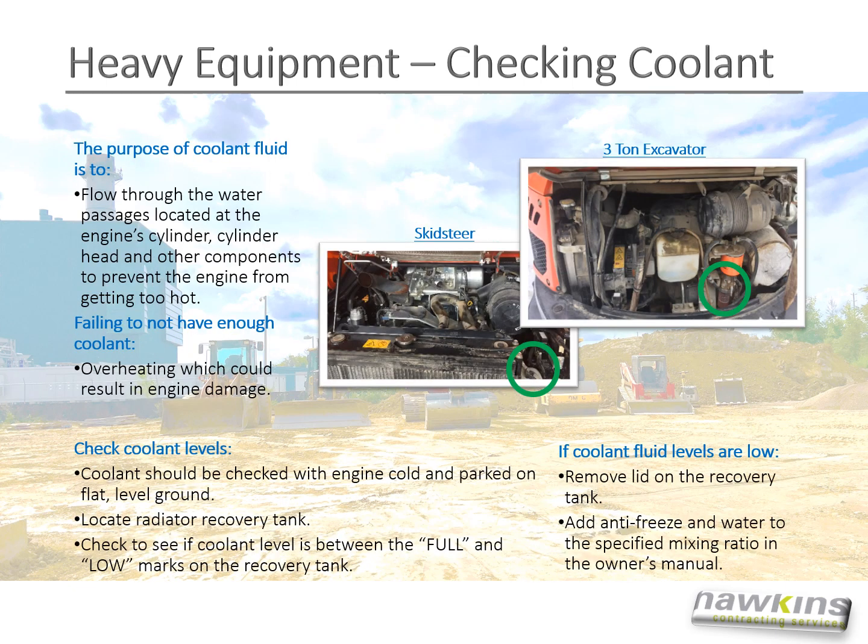Checking coolant fluid. Coolant should be checked with engine cold and parked on flat, level ground. Locate the radiator recovery tank. Check to see if coolant level is between the full and low marks on the recovery tank. If coolant fluids are low, remove the lid on the recovery tank. Add antifreeze and water to the specific mixing ratio in the owner's manual.